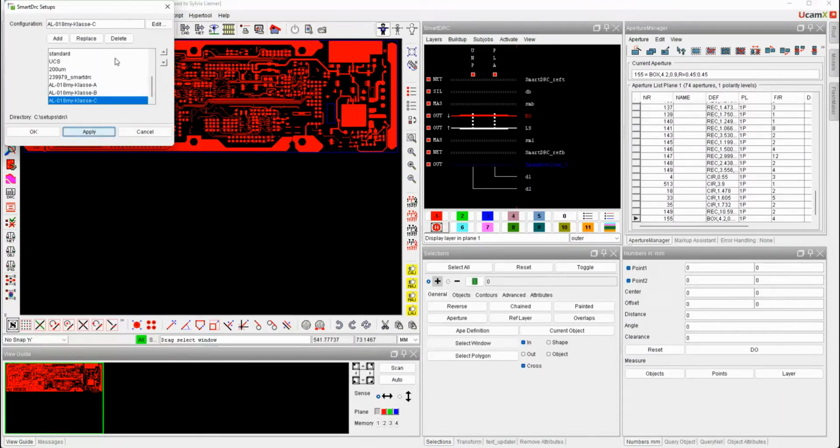Every manufacturer of PCBs is handling the DRC check differently. For example, some prefer to go through the DRC based on the check type, like this one here: first the pads and holes, then the annular rings, the clearances, the lines and silk screens, and some special tests. And in this case, they repair after every check before doing the next. Others prefer to do it all in one run and filter through the found issues via error handling. I will explain that a little bit later.